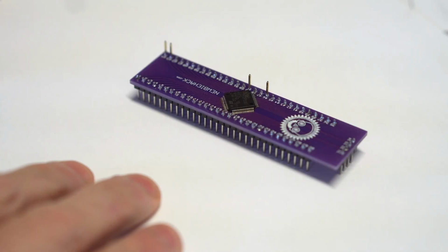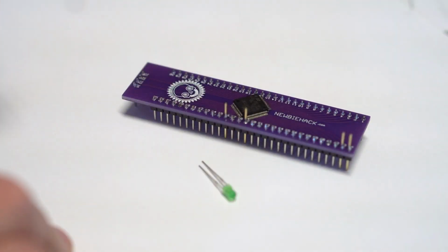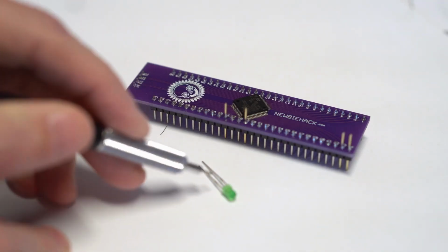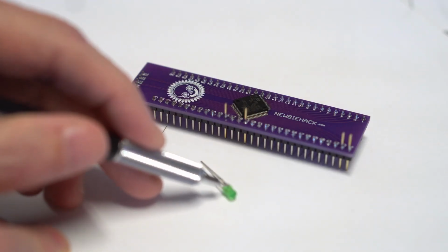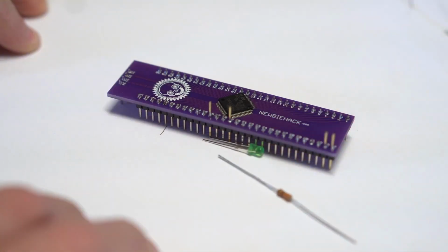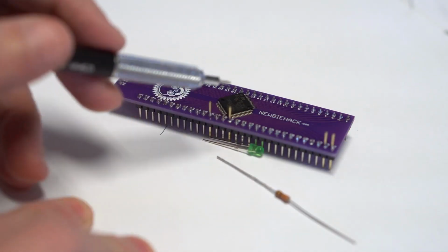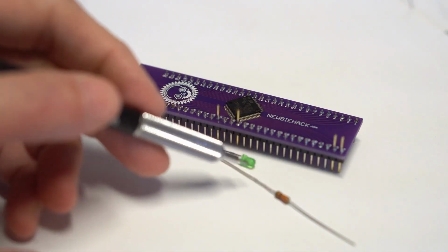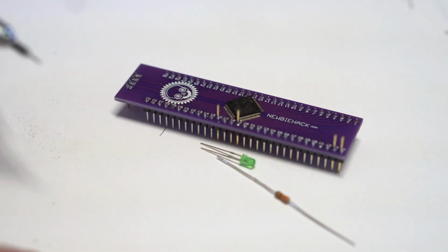Let's put these operations into practice. So I'm going to take an LED and connect it to pin number 37, which is right here. The LED needs a resistor to reduce its voltage, because if we don't put a resistor on here, it's going to burn the LED out. So I'm going to use a 330 ohm resistor. I probably don't need something this large because this is already at 3.3 volts, but a 330 ohm resistor will just make the LED a little bit more dim than its brightest.